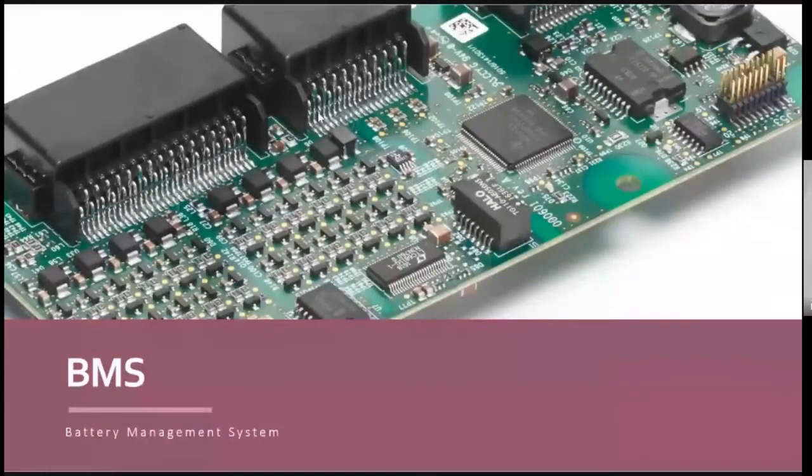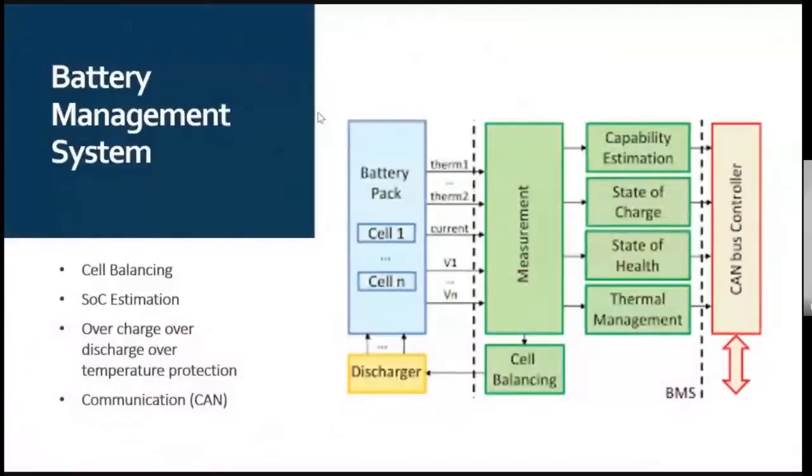And all these things are automotive compliant. There is the AEC-Q100 standard. Every component, including diodes and MOSFETs, should meet automotive quality. That's the only challenge we are facing here. Here they're using Texas Instruments automotive qualified microcontrollers. We'll discuss different series of microcontrollers.